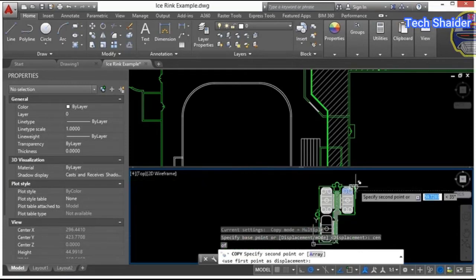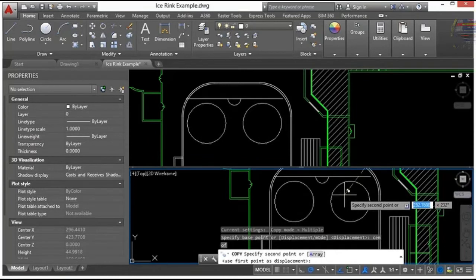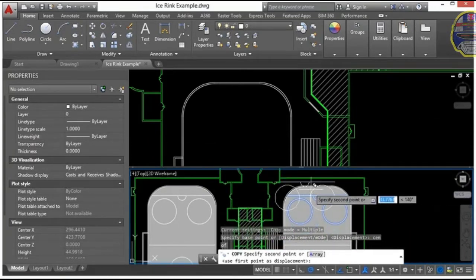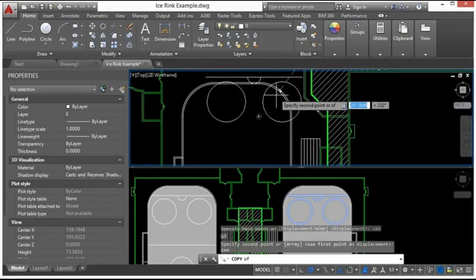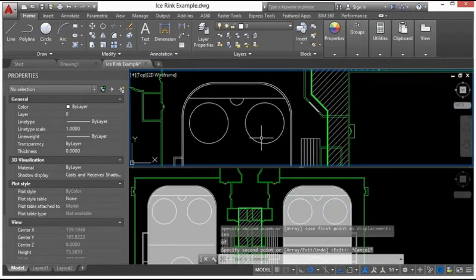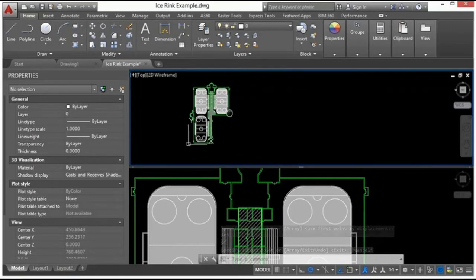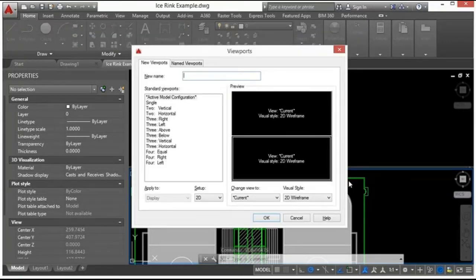I can take the time to zoom out, pan around, and zoom back in, and you can see whatever I have to do is going to show up there. Or while I'm working here, I copy it, I just come to this viewport, and I'm instantly there. Now this drawing site isn't extremely large, but it is quite big. And so I can use that to go back and forth very quickly to see what I'm doing in one spot while working in another. Now you can type in Viewports, or you can type in Viewports. Either way, it'll get you to the same place.